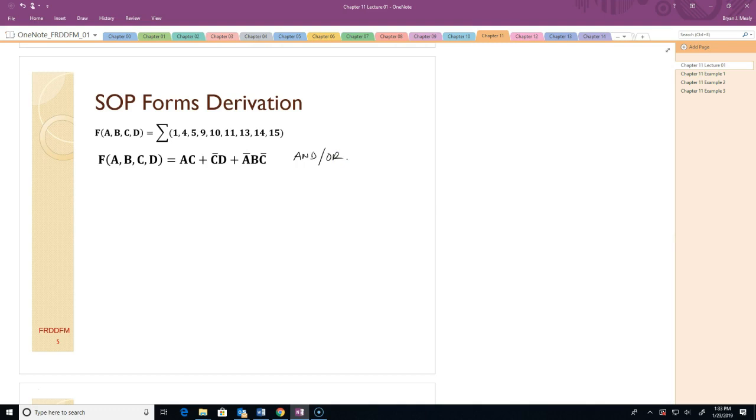And I don't have this memorized other than the fact that the starting point is to double complement this. Okay, so once I double complement that, I'm going to apply De Morgan's theorem one time with one of those complements and bring the result down. So the AC, there it is. So we've brought down one of those overbars by using De Morgan's theorem, and we've stopped at this point. And so this, I'm just going to write this down. This is a classic NAND form.